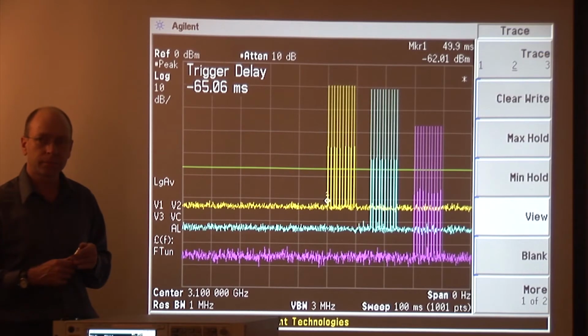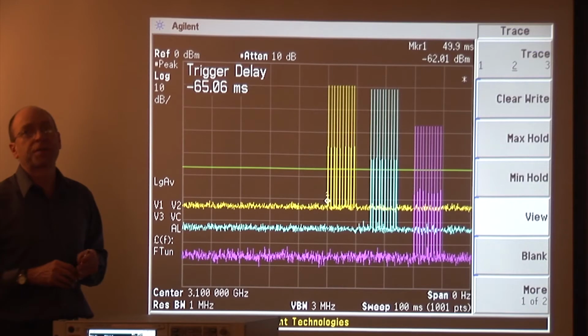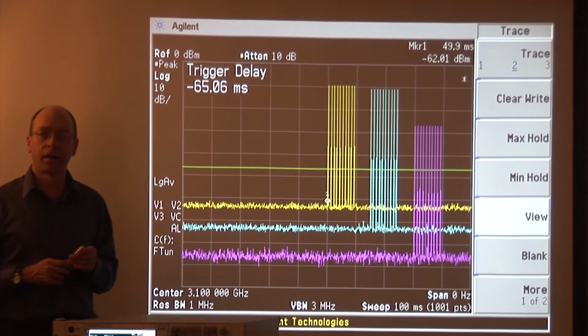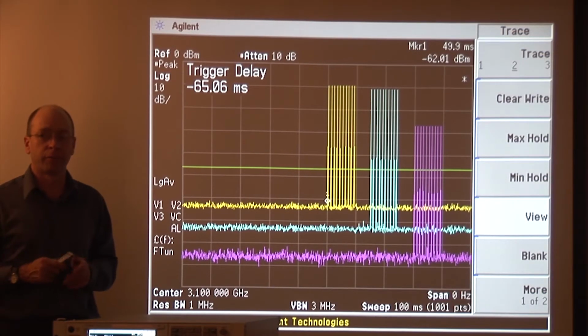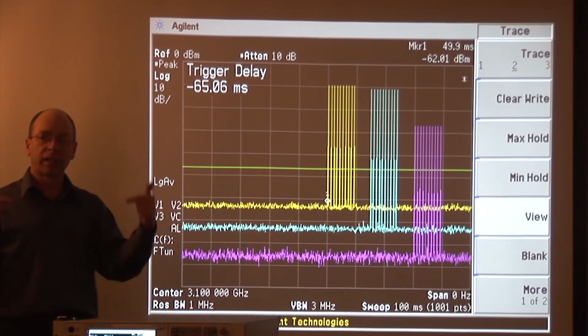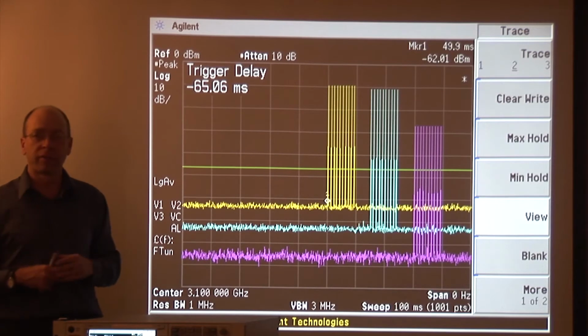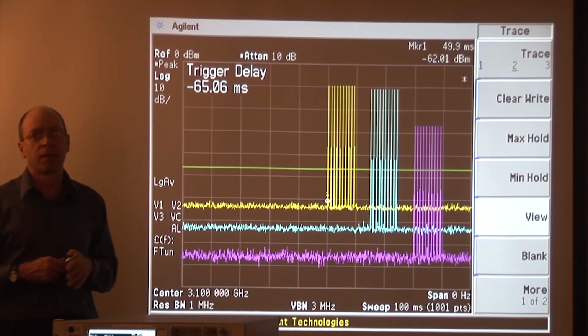What sort of precision are you seeking in these types of measurements? Good question. A dB, if we can get it. 1.5 dB is probably more realistic in terms of what we can actually get. And remember that the measurement that we're doing is a relative measurement. We're measuring the power in the spectrum relative to the power at the fundamental. So the relative offset is what's important. But we'd like to nevertheless be within about a dB or so.